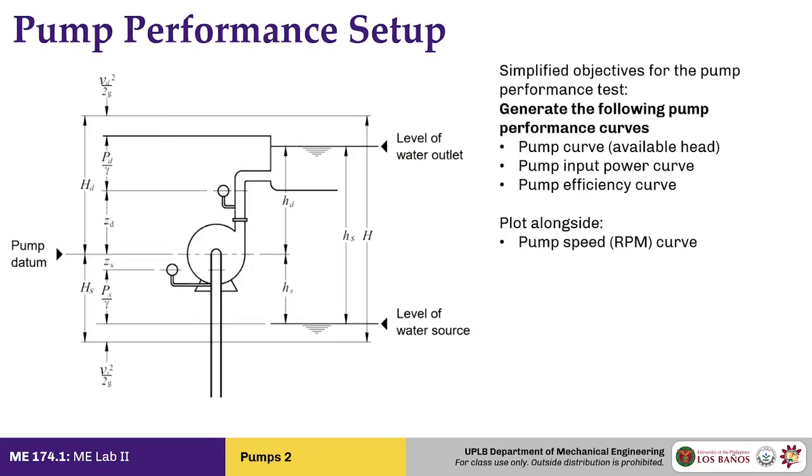Now, there used to be a test for net positive suction head in the standards. I think the engineer for next meeting will ask about that. However, the revised version no longer has the NPSH test. So we'll only be doing the pump performance test. Essentially, the discharge head depending on the flow rate that can be supplied.